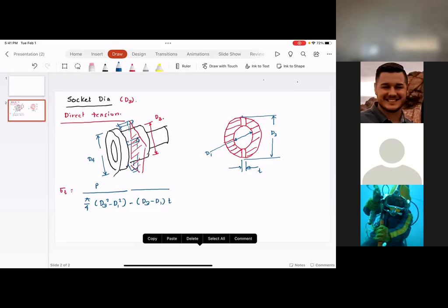Then the next dimension is the thickness. Thickness of the collar is not an assembly dimension, so you don't have to have very high tolerances on it. The outside diameter of the collar can have slightly oversized dimensions. That's totally fine. So the most important dimensions that should have tolerances are the dimensions that will facilitate assembly. Does that answer your question, Alexander?